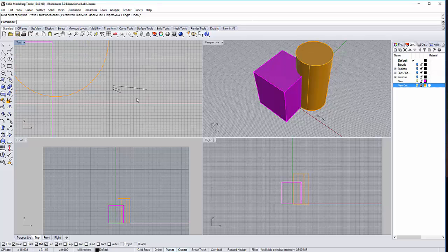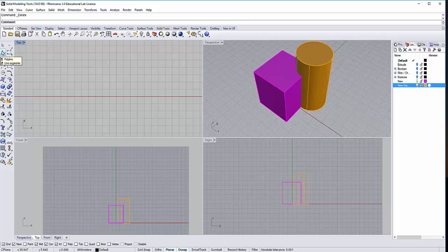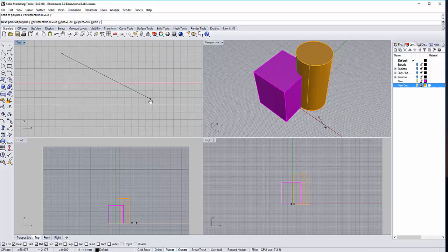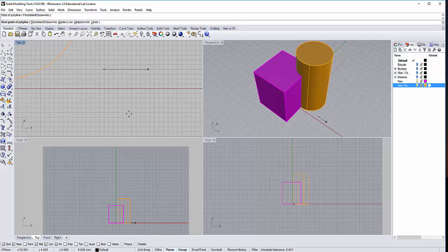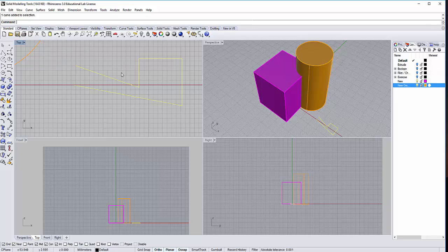Once you try it, let's delete this. I'm going to show you the orthographic tool. Same, let's use the line tool. The orthographic snap here will snap it to 90 degrees. If you want 45 degrees, if you want to unsnap it, you must press shift. Then you can click wherever you want. Can you see? Once done, press enter. Try that button too. Once done, delete. Get very familiar with all the buttons.